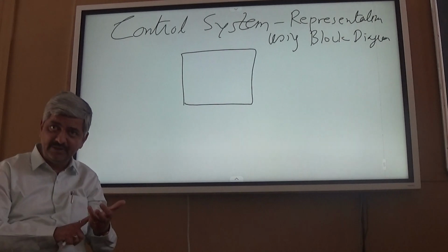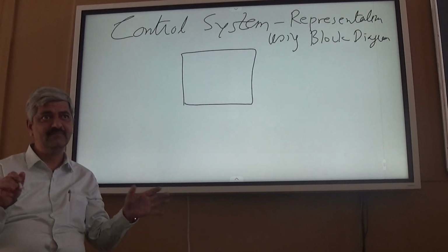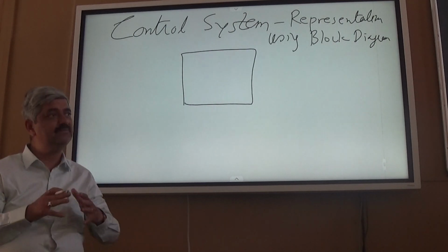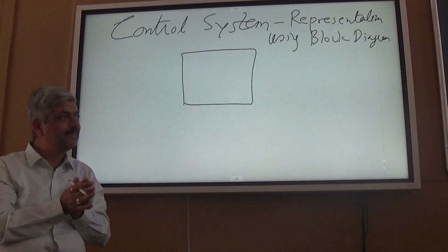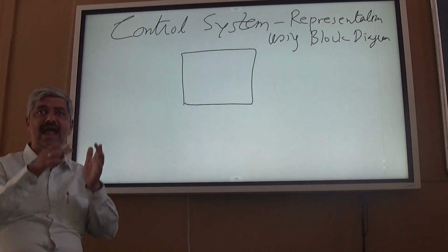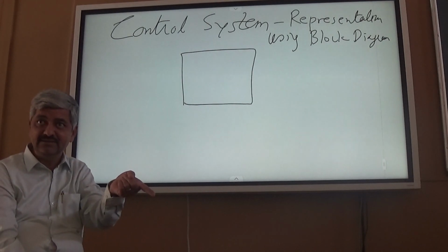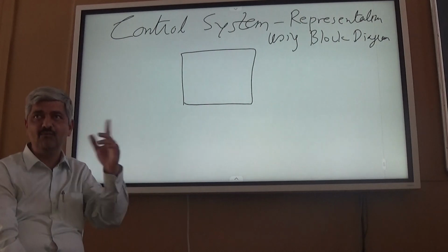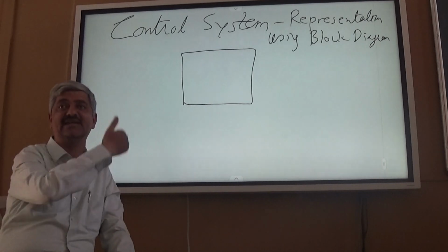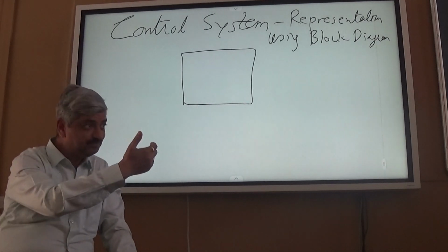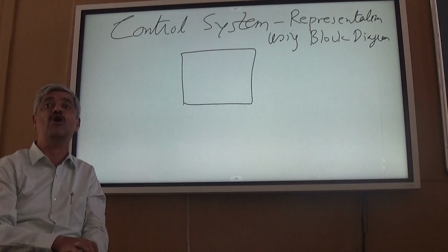Now we add op-amp, that is amplifier, and adder. So once that is done, we have control systems. The linear circuits or circuit theory was primarily consisting of passive systems, but here the major focus is on active systems, because we can't have a concept of feedback unless we incorporate active elements. How can we incorporate the concept of feedback wherein we have to add something by scaling? Scaling with gain less than 1 is possible, but adding is not possible unless we use an operational amplifier.